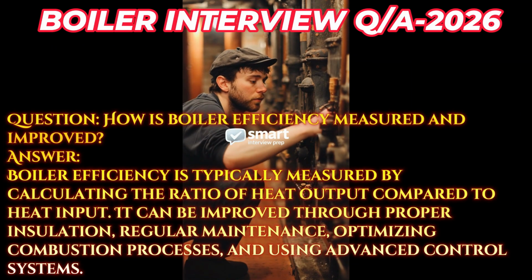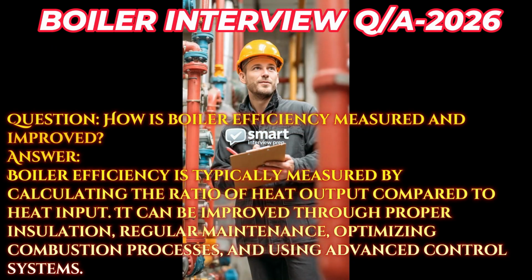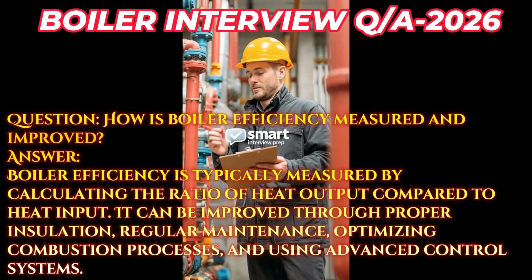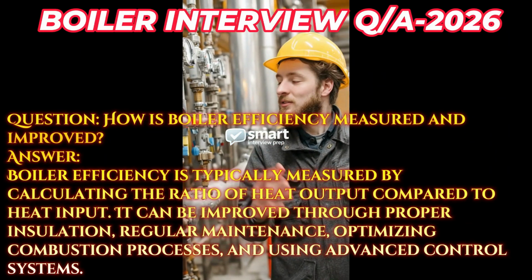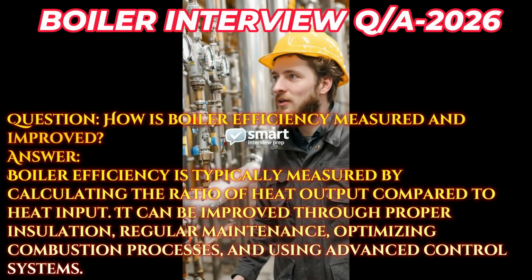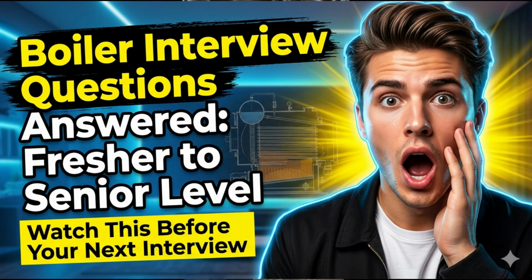Question. How is boiler efficiency measured and improved? Answer. Boiler efficiency is typically measured by calculating the ratio of heat output compared to heat input. It can be improved through proper insulation, regular maintenance, optimizing combustion processes, and using advanced control systems.